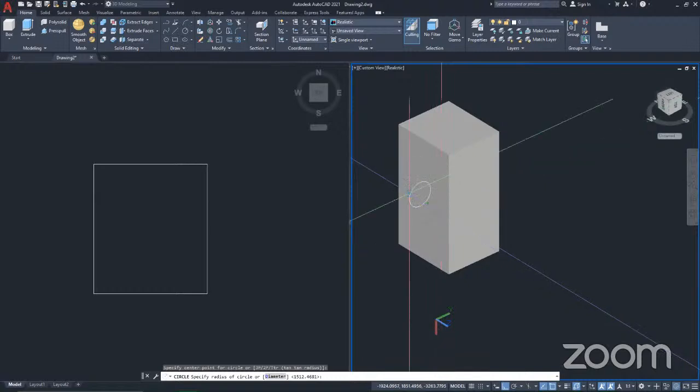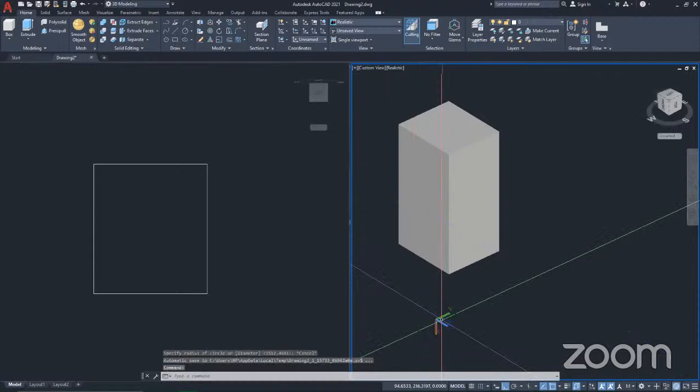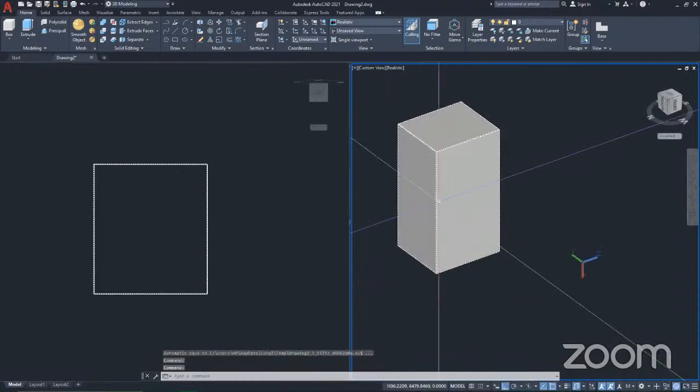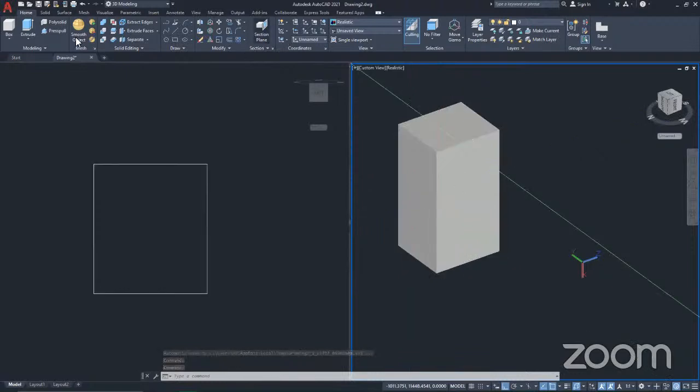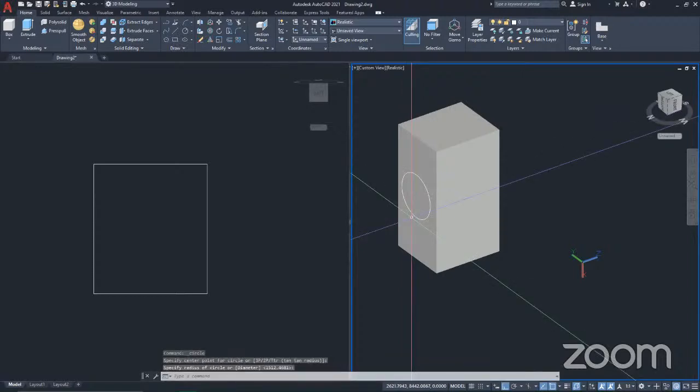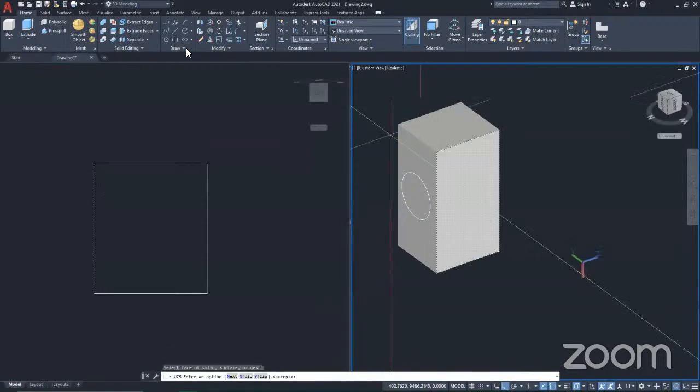There is something wrong there. I did something. I aligned it to this other face. See where the XY plane is. I aligned it to this other face here, and that's an error. Let me confirm it first before actually agreeing. Okay, you see, I aligned it to this face, which is wrong. I wasn't supposed to align it to that face. So I come back here, select this face, and I select this face. That's my XY. And now I want to draw.